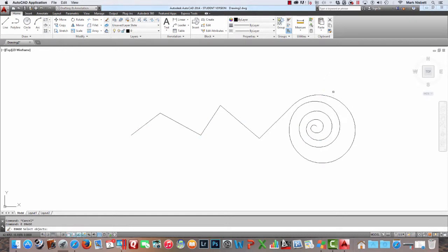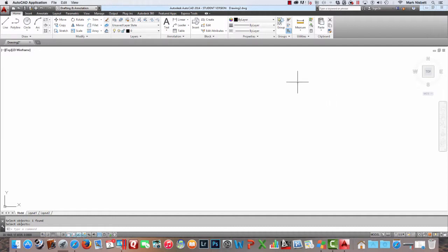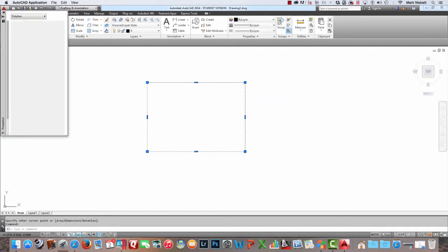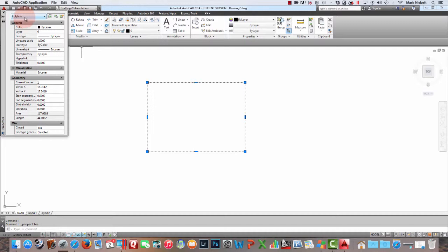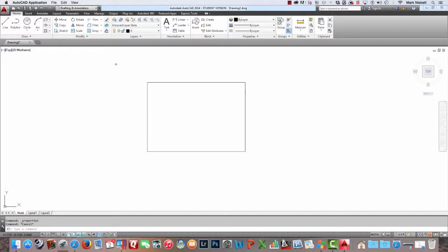All right, so there's many different advantages to using polylines. One is the offset command. One thing that is a polyline is a rectangle. Even though a rectangle shows up as its own command, when I pick this, this is actually a polyline object. It's four lines connected together. If we look at the properties, notice up top it's called a polyline. It's not called a rectangle, it's called a polyline. Even though the command originates as a rectangle, it actually generates a polyline.